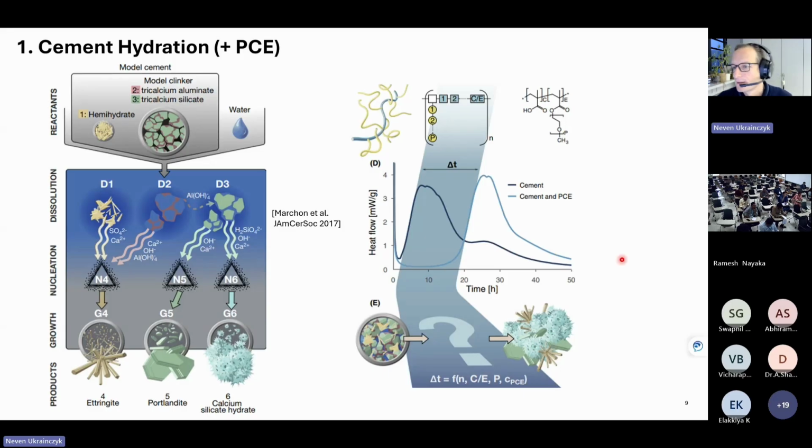Here of course we need to add chemicals, and these are the plasticizers if we want to control the rheology, or also the setting time. Actually, they also increase the setting time, so we need to add more additives, because this 20-hour working time or 15-hour is too much. After a few hours, the concrete should start setting and then also hardening, and we can control the rate of hardening.